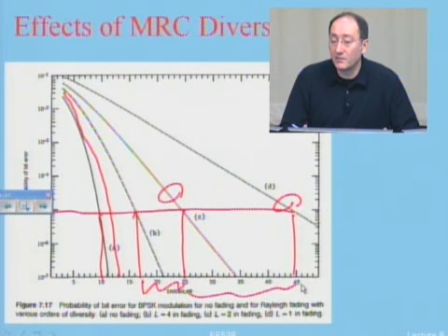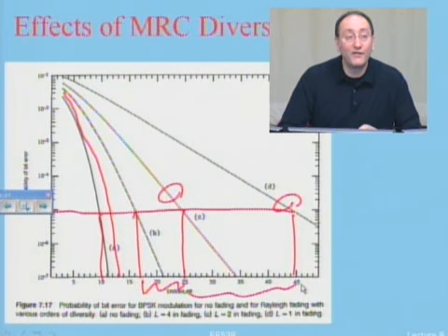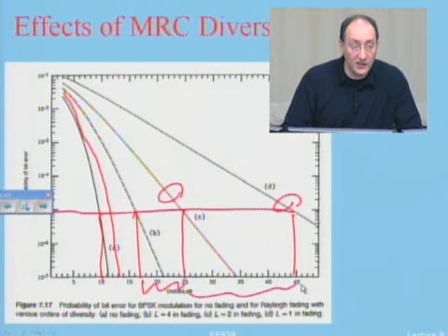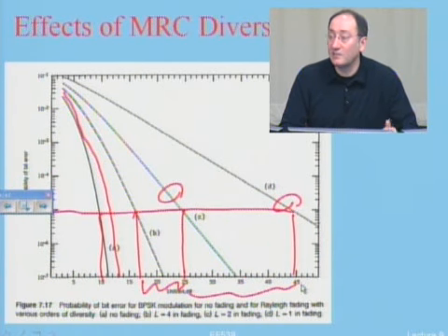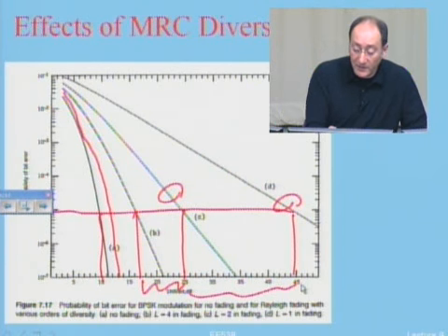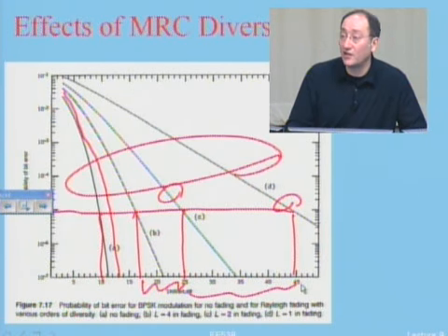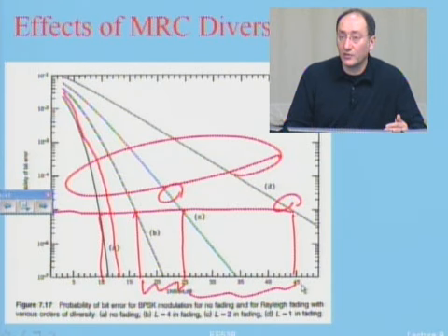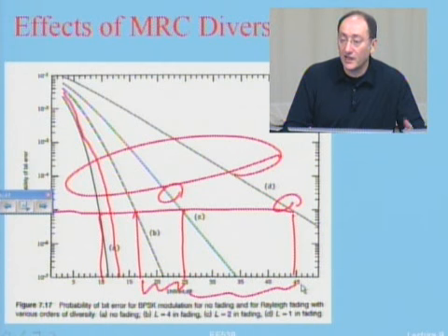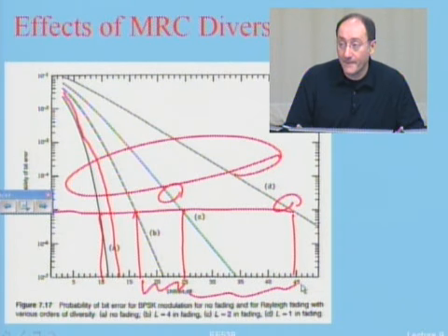Fading is the cause of problems in radio channels. Go and find methods to create diversity, because diversity is the remedy. How effective is diversity? If the diversity is independent, this is how effective it is. But just to start with, I told you two types of games you can play to provide diversity. One is you can add coding. The other is you can add multiple antennas.